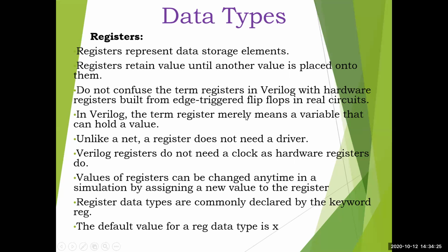In Verilog, the term register merely means a variable that can hold a value. Only this is the definition. A variable that can hold a value for a certain period of time is declared as a register. Unlike a net, a register does not need a driver. In a net, compulsorily something should be connected to that, a driver. Here, that is not the case.